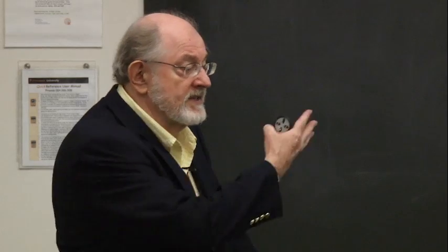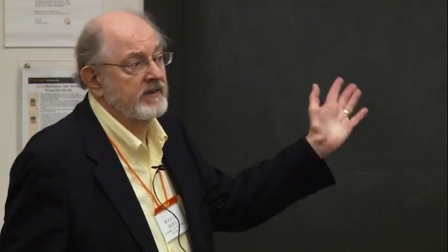And in fact, I'm going to get to discussing that a little bit more next, because we'll be talking about spark ignition engines in a minute. And as I told you last time, if you're looking at a turbulent flame, with all those flamelets inside that computational cell that you're not resolving, now you have a problem. But for this type of combustion, where essentially the combustion is controlled by large-scale mixing, you don't need to worry about turbulent chemistry interaction.